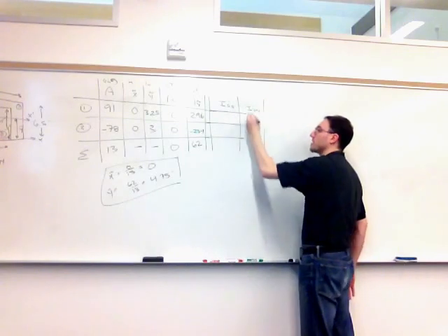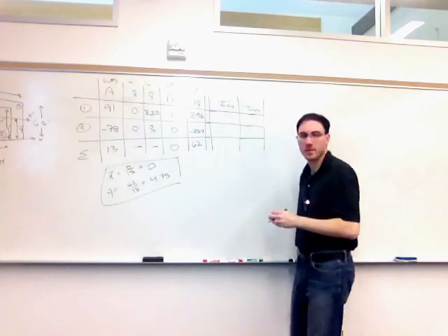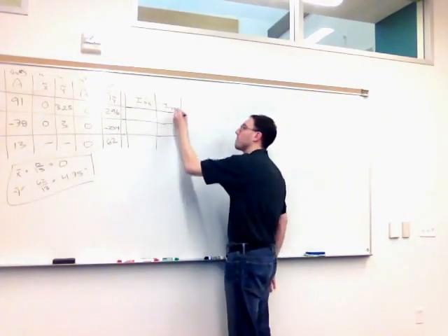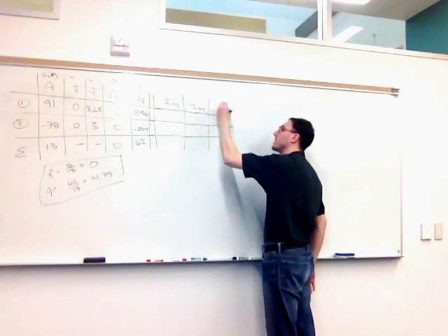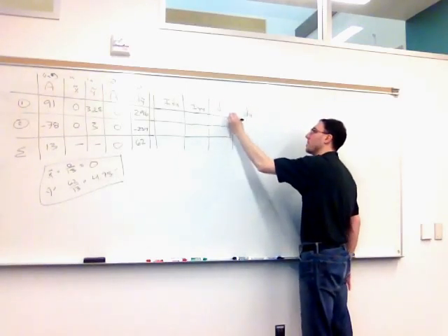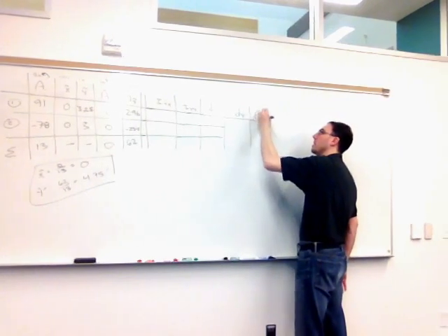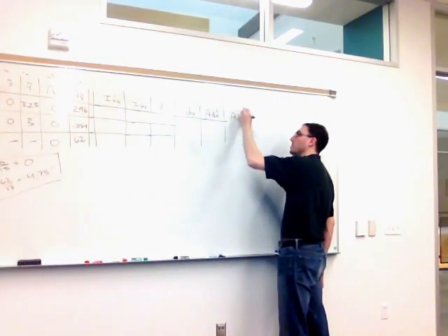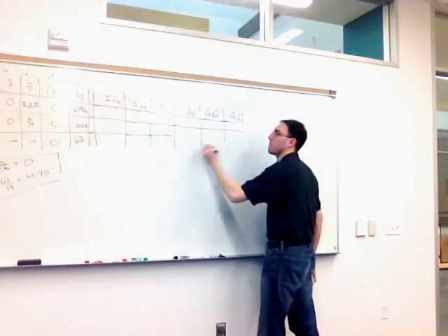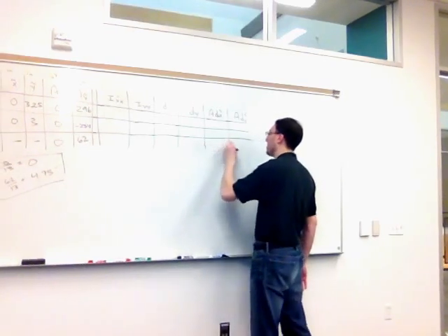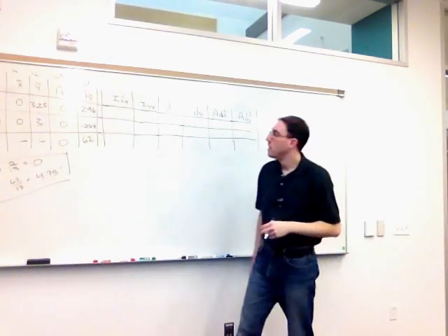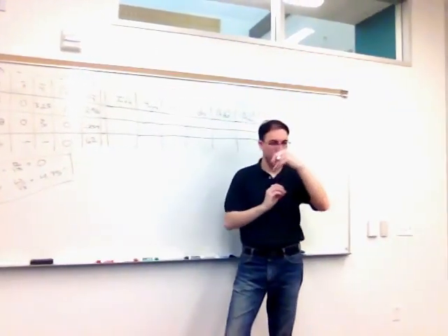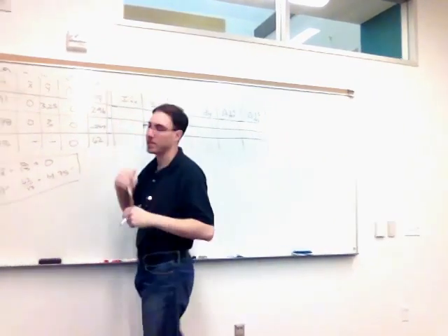Now we move on to, we want both Ixx and Iyy. For each shape, we're going to find its moment about its horizontal centroidal axis and its vertical centroidal axis. That's the Ixx prime, Iyy prime. We then also need to find this dx value, this dy value, and then the full adjustment for the parallel axis, Adx squared and Ady squared. We have to always be careful, are we talking about the horizontal bending or the vertical bending in this case, or which axis we're bending about.